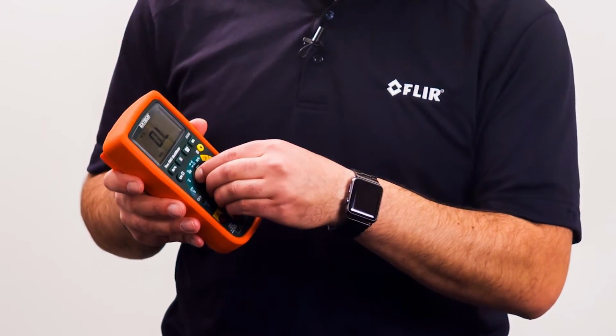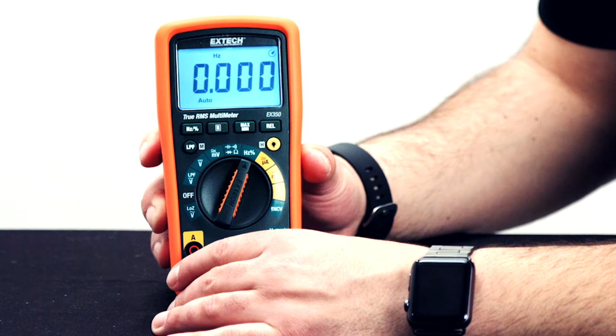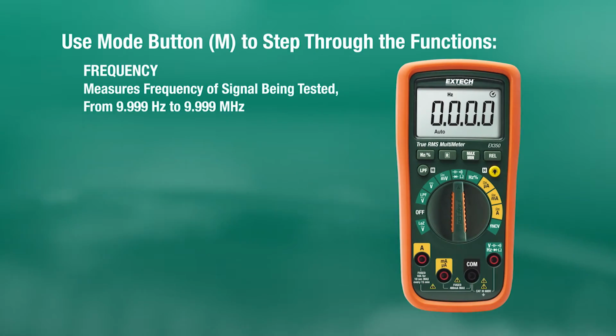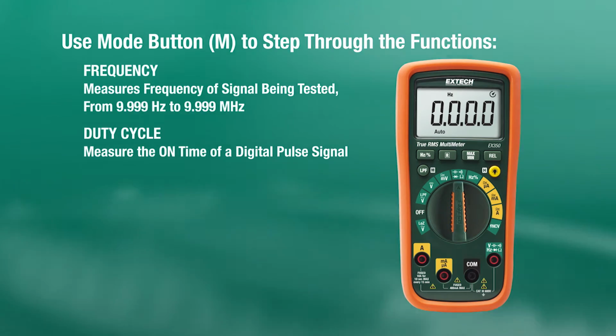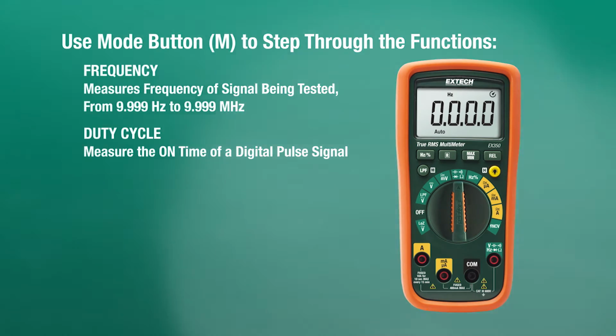Turning the wheel to the next setting, frequency and duty cycle. Similar to the previous setting, on this meter we use the mode function to toggle between the modes. Frequency measures the frequency of the signal being tested. Duty cycle measures the on-time of a digital pulse signal.